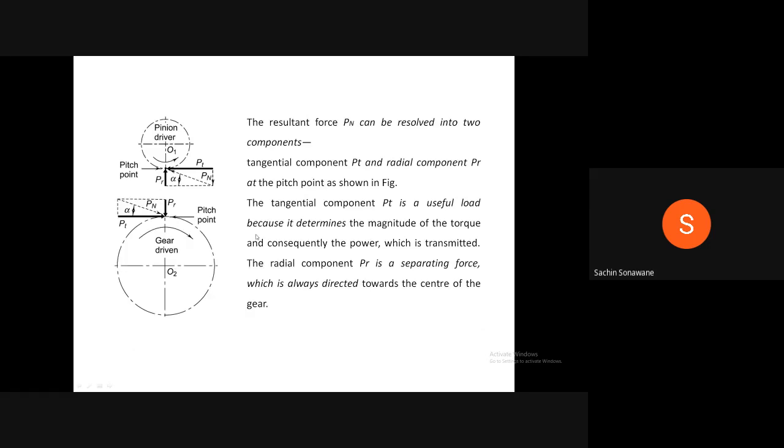Now we will resolve that force Pn into two components. First is the vertical component and second is the horizontal component. The resultant force Pn can be resolved into the tangential component, that is the horizontal component, and the radial component PR, also known as the vertical component, at the pitch point as shown in the figure.